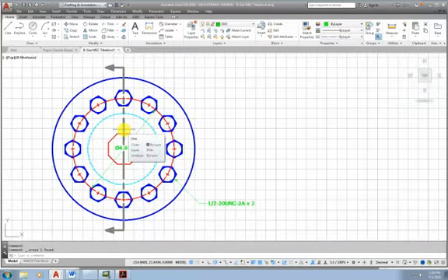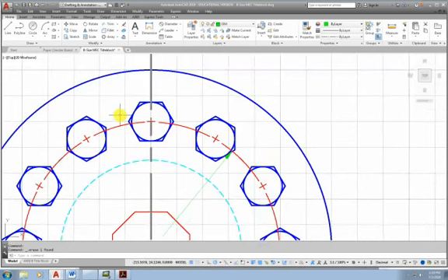covered up by the cutting plane line, and so it's allowed. When we would draw with a pencil, we would do things like this all the time. The automation of the technology has a tendency to do things like draw the lines right over the dimensions, and good drafting techniques can alleviate that if you have an understanding of them.